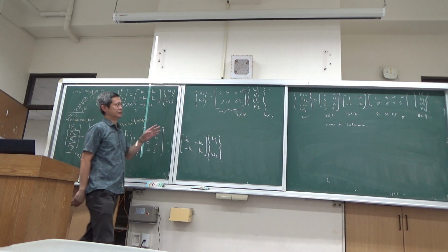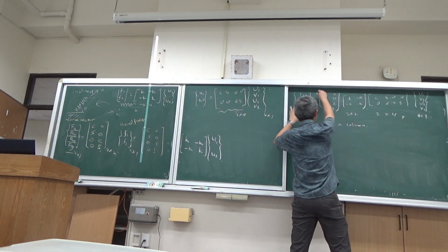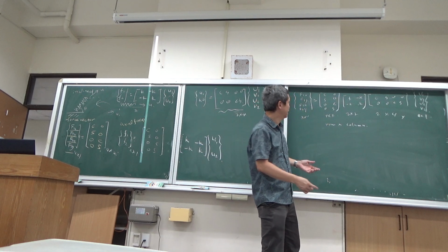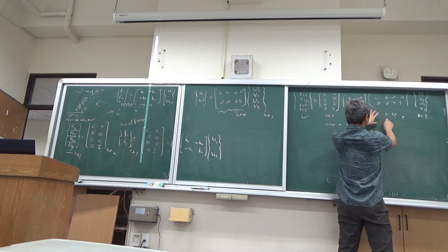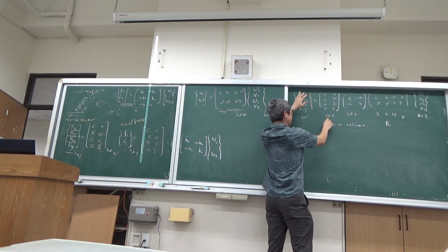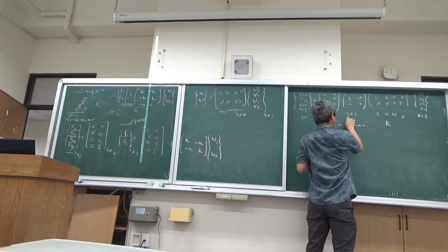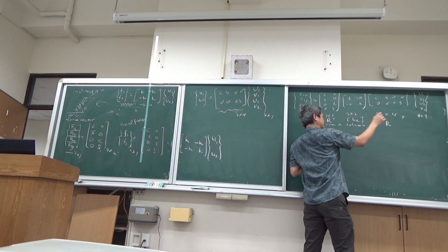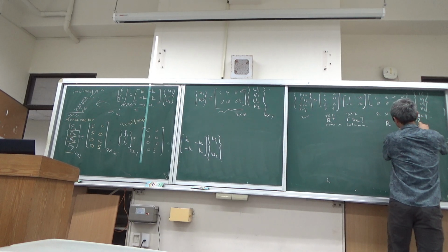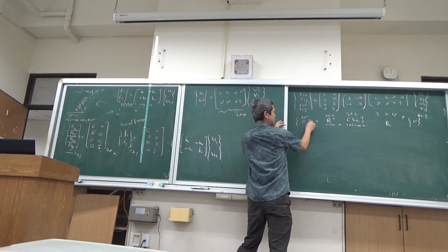So with this, we're going to do some operation because we know this is my global stiffness matrix. Okay, if I define this as my rotational matrix, you can see this is the transpose of my rotational matrix and my small element stiffness. And then this one is the global displacement vector. It's equal to my global force vector.